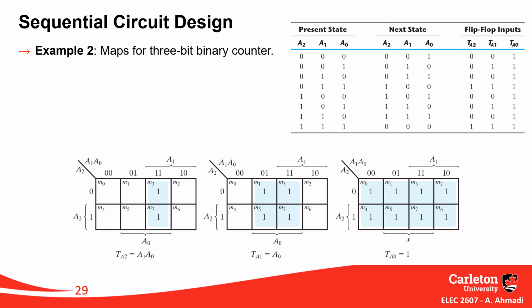The transition table for a counter will be something like what we have here. You see transition from 0 to 1, from 1 to 0 as numbers. But in terms of states, you have to check that this 0 is transferred to 1, this 0 stays 0, and this 0 stays at 0, right? How many flip-flops do I need to implement this? Since I have 3 variables, I need 3 flip-flops. Probably the most popular or the simplest implementation of a counter will be using T flip-flops.